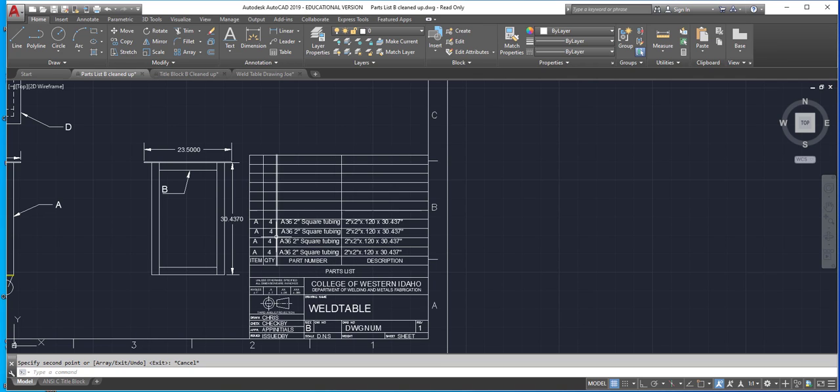And the reason this works out is because then you don't have to come through and figure out your spaces and everything else. Now at this point I can just come through and do my editable text. So here's A, or that's B. Okay, and I can come over. It's still 2-inch tubing, 2x2, 120 wall, but let's say my measurement is well, we're 23.5 minus 2, 4, 6, and 8. So we're going to be 23.5 minus 8, so 18.500 inches. Okay?